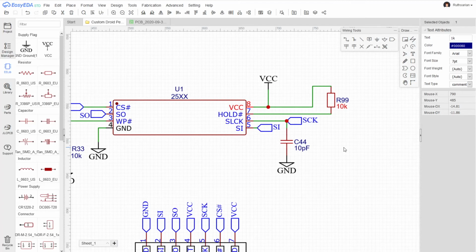So if you're in an instance where your programmer is going to try to sink the current coming in on that pin, that is, if there was a short, it would damage your programmer. Well, that resistor now is going to limit the amount of current coming in through the power pin to a very small amount, and that should be less than the amount that would cause any potential damage to your chip programmer. So that's why I've included it on my previous personality chip designs. That's why I'm going to include it here.